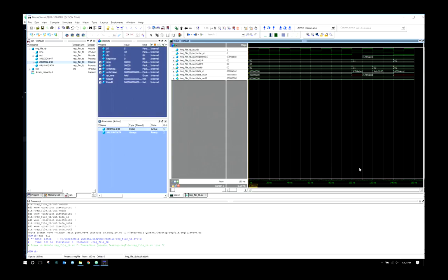At the first test, at the start of 100 nanoseconds, I was giving it a write address. I was giving it a value of 0, 1 in hex, which means register 1. And then I was giving it a data in of this hex value right here. And what else was I doing? I was giving a write enable. So if you see write enable, it got asserted at 100 nanoseconds. What that's saying is to write the value of data in to register 1.